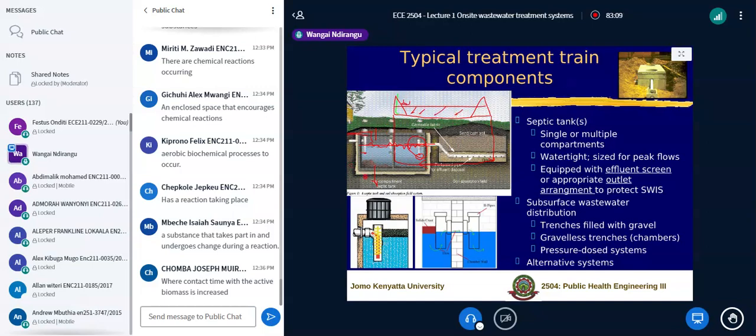Some matter like what you have seen here settles. If this builds up somewhere here, it will keep on recirculating the settled matter. So the depth is between 1 to 1.8 meters, 1.2 to 1.5 being more the rule of thumb.